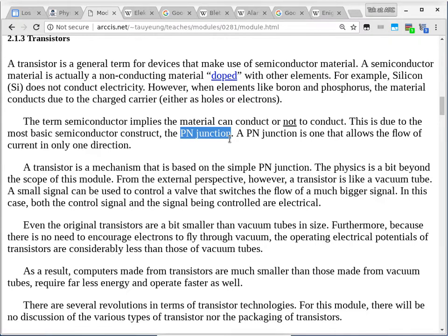Okay, so when you make a silicon crystal, one silicon connects to 4 other silicon, and then each of those silicon connects to 4 silicon, and so on and so forth. So you don't have any free electrons floating around to conduct electricity. That's why it's not conducting.